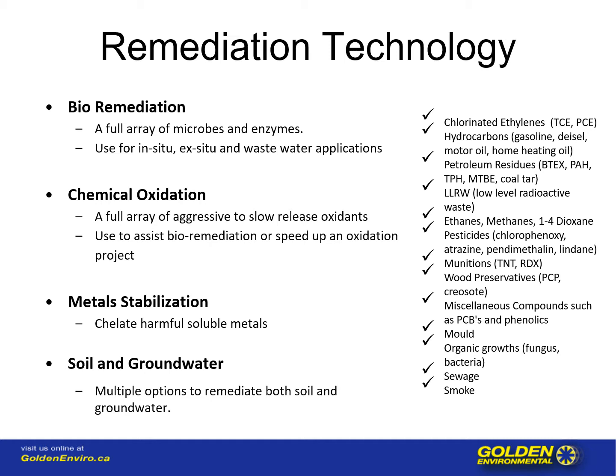Both the bioremediation and the chemical oxidation do remediate the soil and the groundwater. We do use mobile treatment units, but not to actually remediate the site, but rather to achieve hydraulic containment, which is a very different purpose. So they're there for a short period of time relative to using a pump and treat system as the remediation